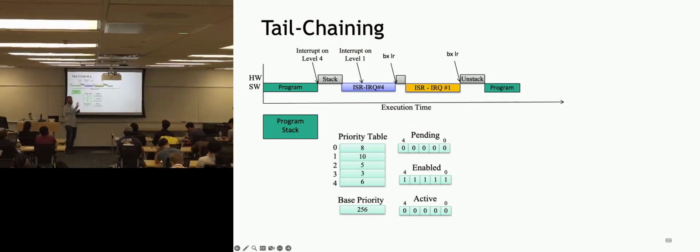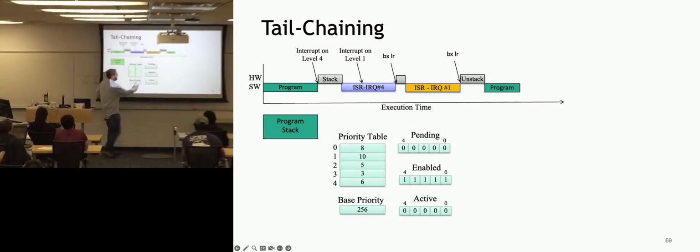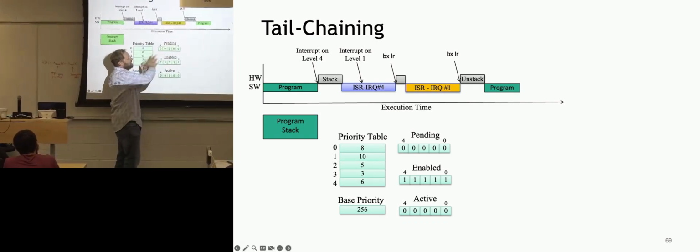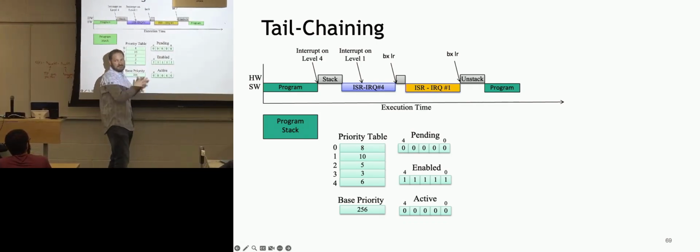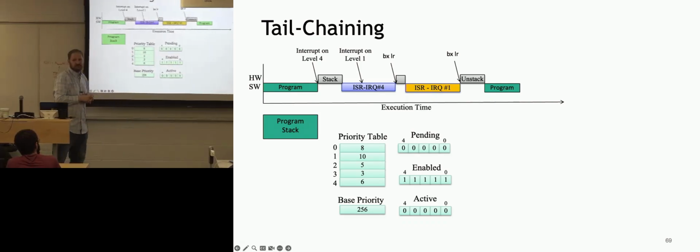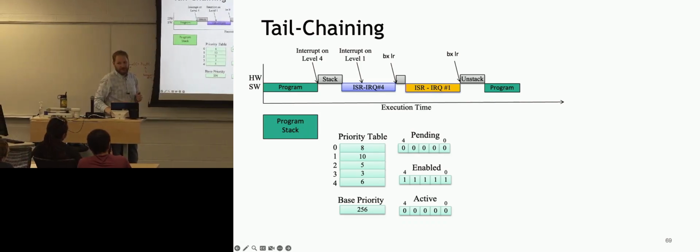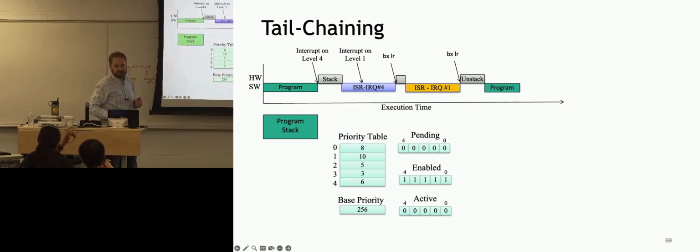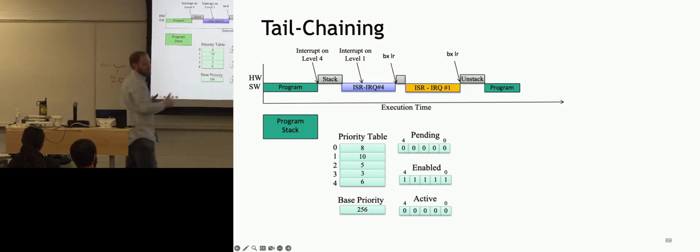Well, the sub priority bits, we're not really showing here. We'd have to have another register channel here that would indicate which one should go first. Okay. What you're saying is you check your preemptive register first, then you check your sub priority if you have a tie. Yep. Yes, and that tie will only exist for pending things.